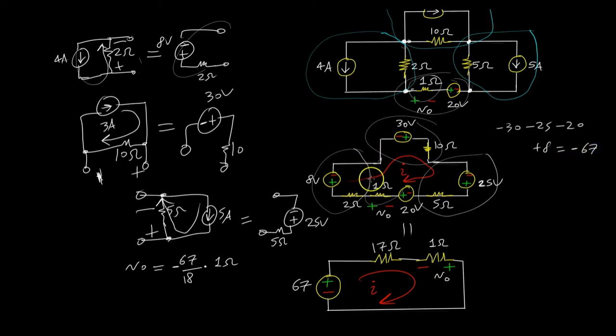But I'm going to recall the direction of the current. The current's going clockwise, so I know when I hit a negative, it's going to have its orientation as below. I follow the clockwise current and hit a negative, and that's the orientation in which my -67 should be. So the negative simply means which polarity my clockwise current meets first. It meets a negative in this way, so it should be in the same direction as the current. That's all that means. I do that, then I combine all the resistors because I know that they share the same current.